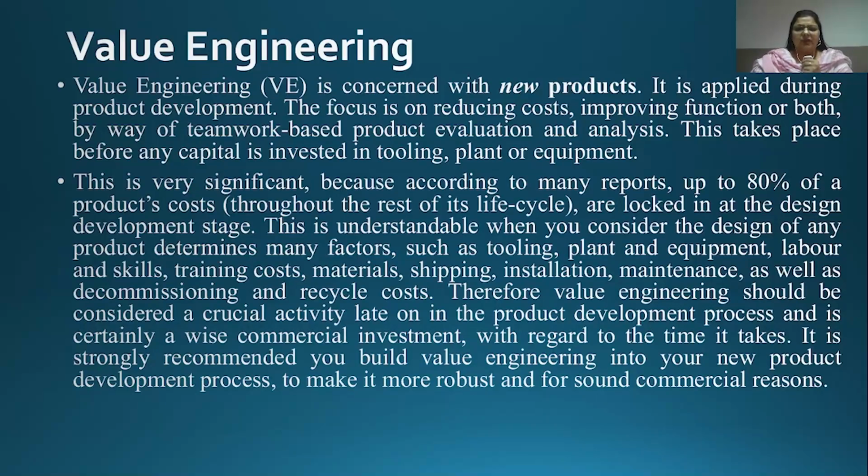This is very significant because, according to many reports, up to 80% of a product's cost throughout the rest of its life cycle is locked in at the design development stage. This is understandable when you consider that the design of any product determines many factors such as tooling, plant and equipment, labor and skills, training cost, material cost, shipping, installing, maintenance, as well as decommissioning and recycling cost.